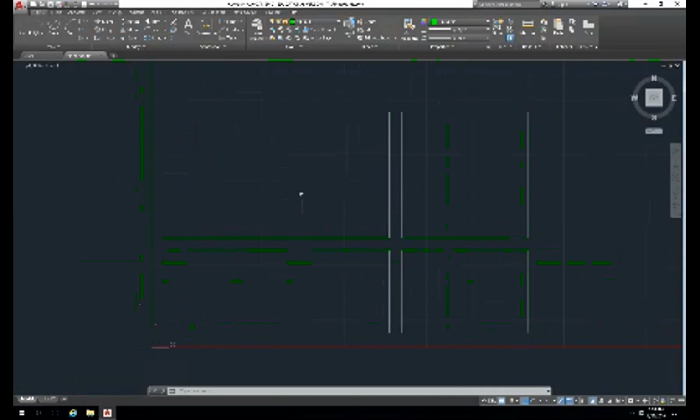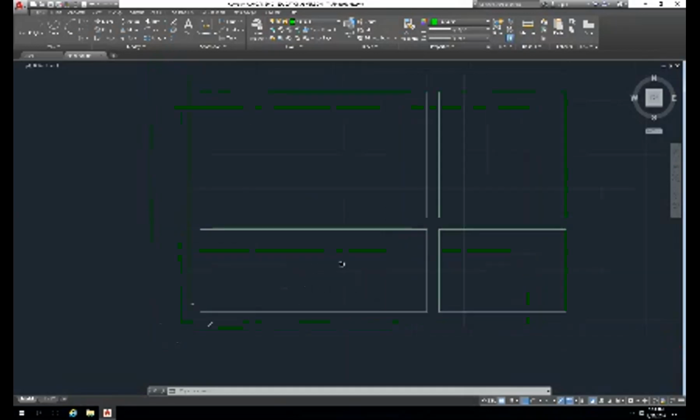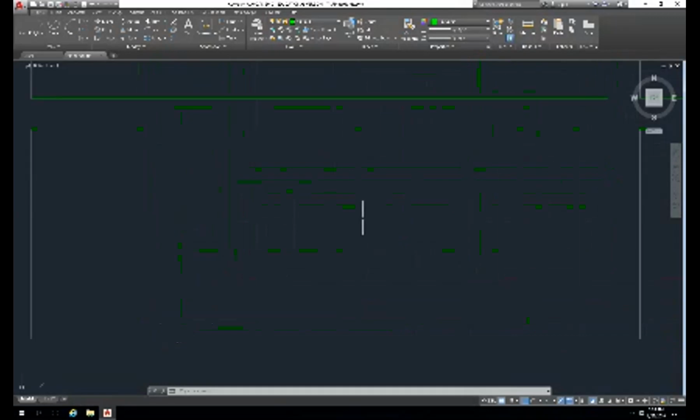So we've got our outer boundaries. Now let's start drawing what we would call features of the object. The instructor wants us to learn how to first complete drawing the feature in all of the views before moving on to another feature. And so he uses the offset command a lot, and it's a nice way to speed up drawing.